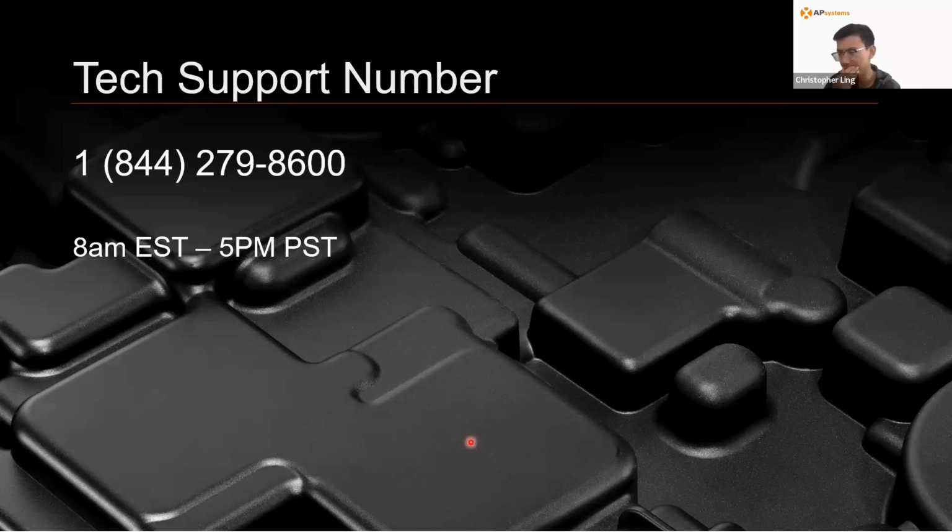I don't know if we sell those. I believe it's possible to get an off-the-shelf Chint meter. But the main thing is that the connection between the off-the-shelf Chint meter and the ECU is Ethernet, through RS-485, with an Ethernet connector. And the main thing you need to make sure of is that you have the right pins connected.